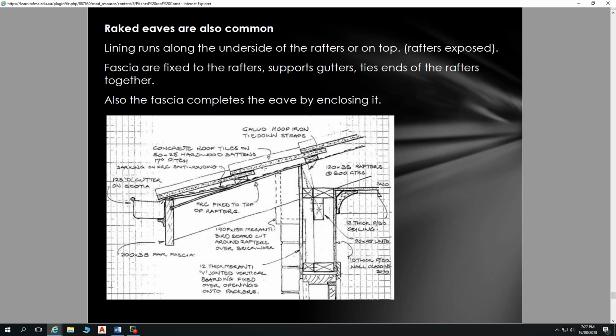and also that space to provide insulation. But also this detail here of a small board, a piece of plywood as an anti-ponding board, to stop that sarking just hanging down here and having water collect in that position. And then that sarking is carried over and laps into our gutter. So for any water that gets under the tiles here, that's carried all the way to the gutter. So our 125D gutter, and we've got a little scotia underneath that.